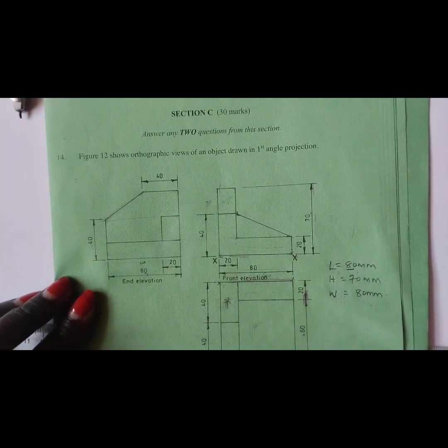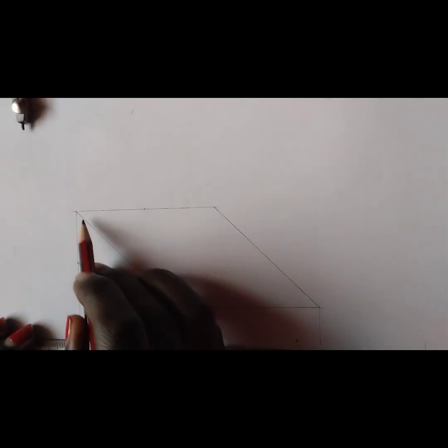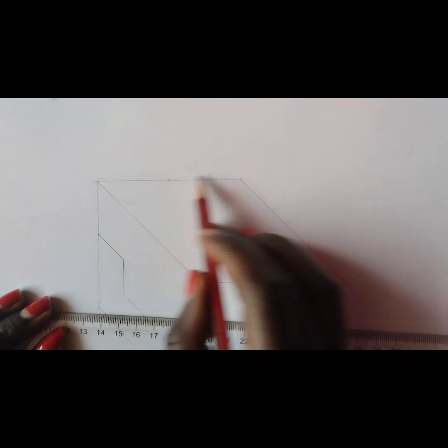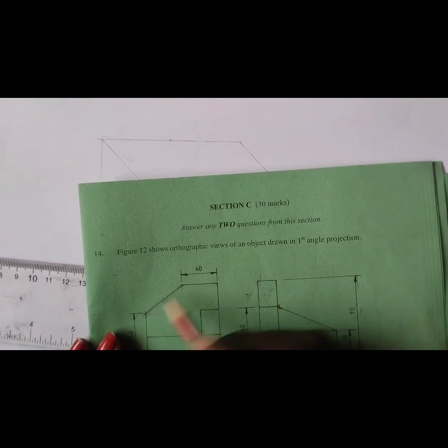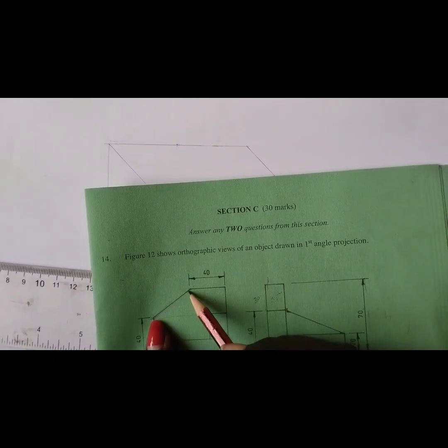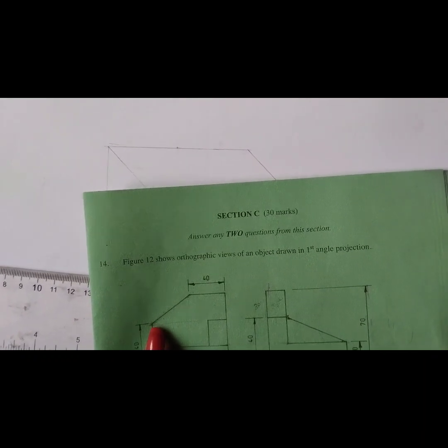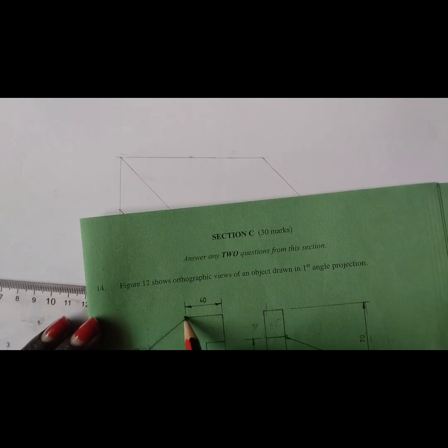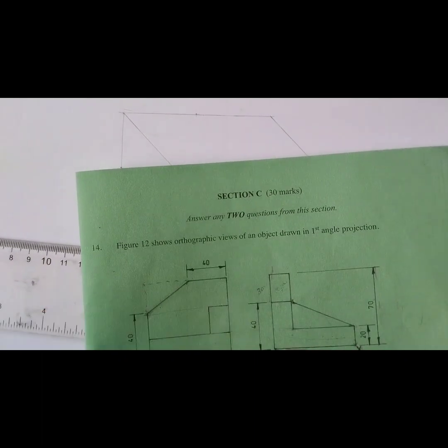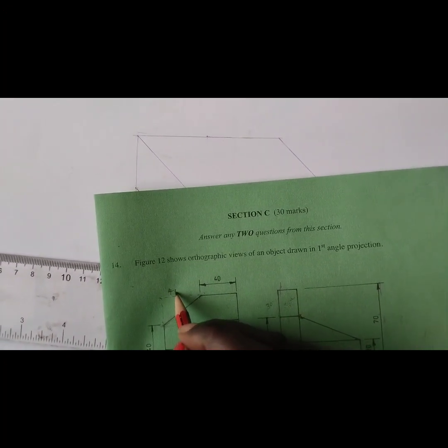So we have this slant height, which is this one in our front elevation, and which is also this part in our plan. So remember now, in our plan we have this length as 80 millimeters. Now we don't have the exact length of this slant, and remember we have it in our end elevation, and it is also part in our plan. So remember from here, if we can extrapolate those lines, so if we have this one is 80, this one is 40, so this part is also 40.